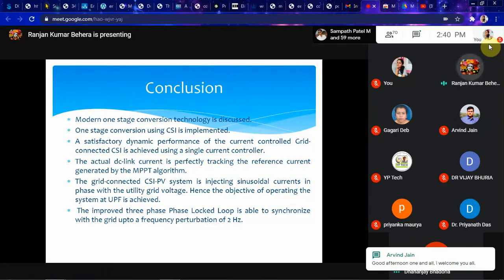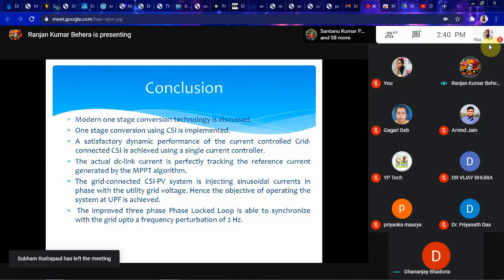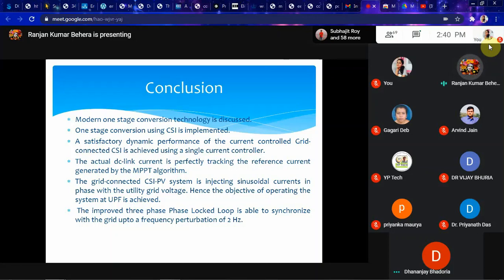During the pulping time, the motor should be very stable. If the motor vibrates a little bit, the quality of paper will go down. So to keep that, people use the current source inverter, because even if there is a small voltage fluctuation in your line, the current source is a constant current source feeding the line, which will not affect it. The current source inverter has a lot of advantages.